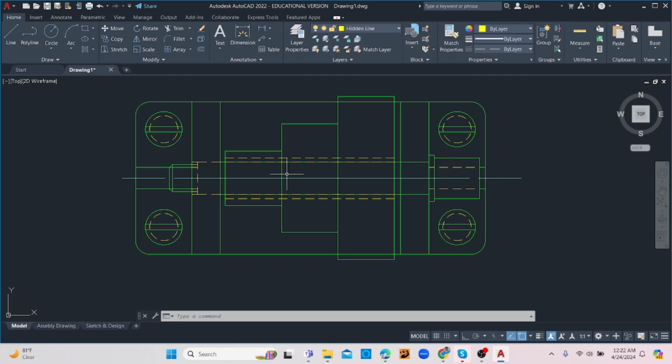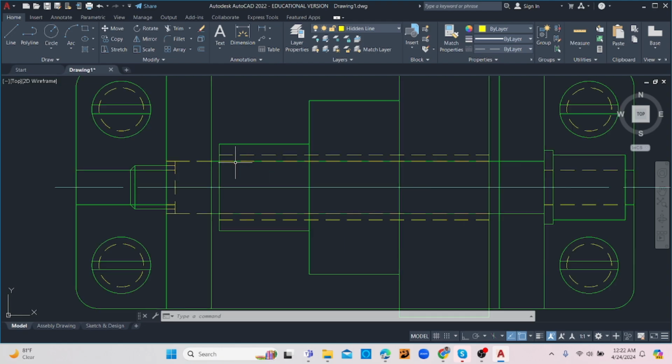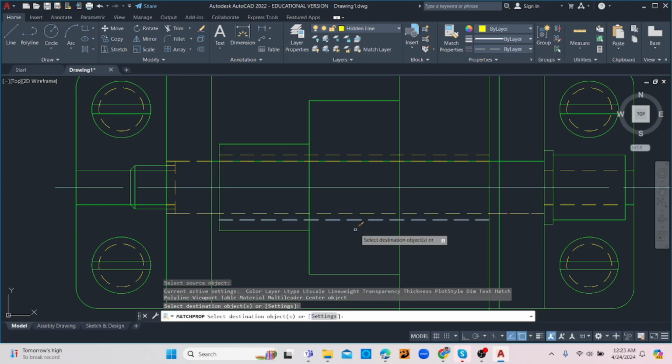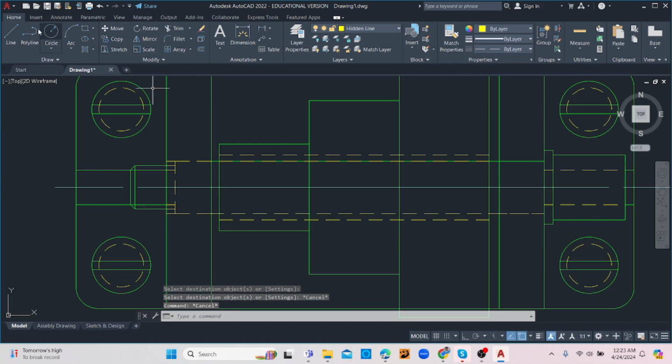Now with our pulley now in place, there are some portions that are also going to be hidden, such as I'm seeing a line here, but I think it is actually the shaft. So what I'm going to be doing is that I'll be selecting these lines here and removing them. This, let me double check, and let's place them on the relevant layer. So this hidden, remember this portion here is solid, so we have to close out that from here to here.